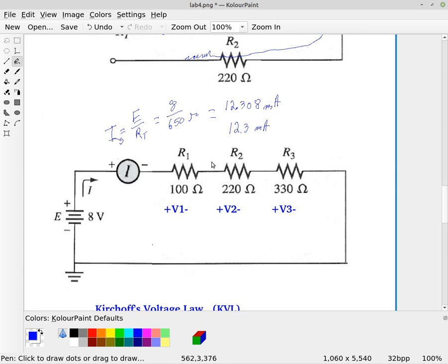However, when we calculate the voltage drop of each one of these, remember, if we want to measure the voltage drop across a single resistor, we measure that in parallel. And we can calculate it using Ohm's law, so that V1 is my current, which is simply I series, times R1.